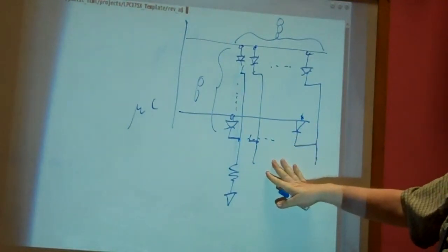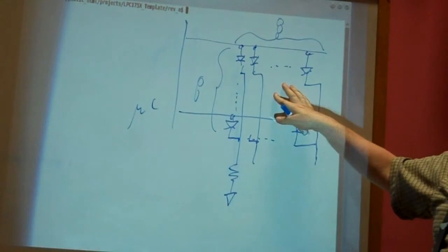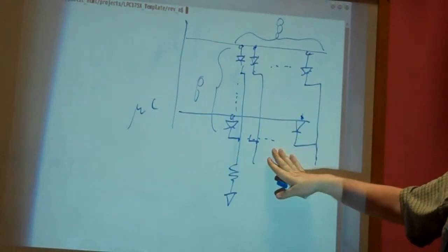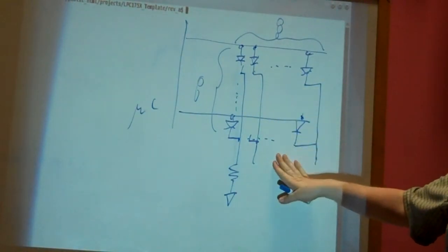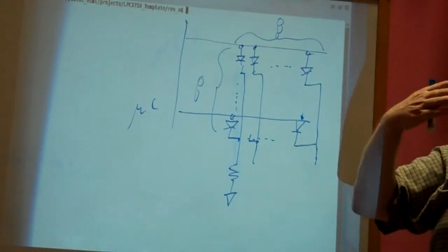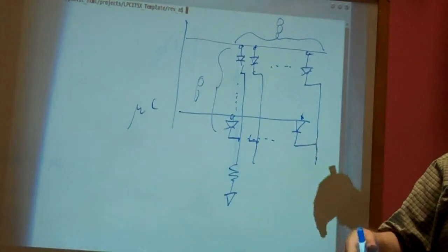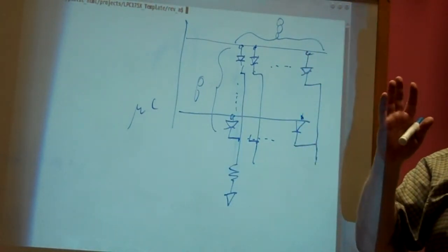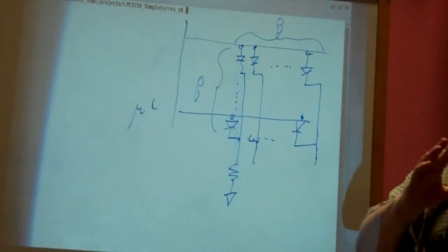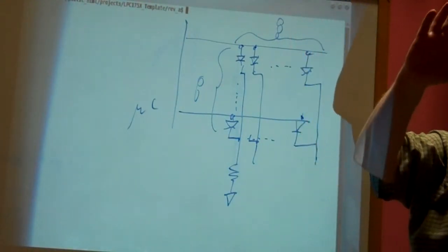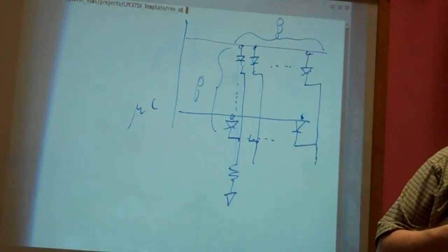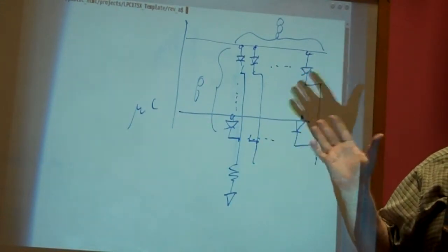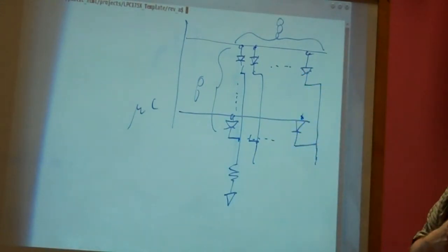So what I'd like you to do is, for the next class, see if you can draw out some sort of LED grid. Okay. We're shooting for 8 by 8, but you may have some problems fitting it all in the schematic. If you need a little space in the schematic, feel free to move the microcontroller over a little, make a little bit of space. You know, you own the schematic. You can do whatever you want.